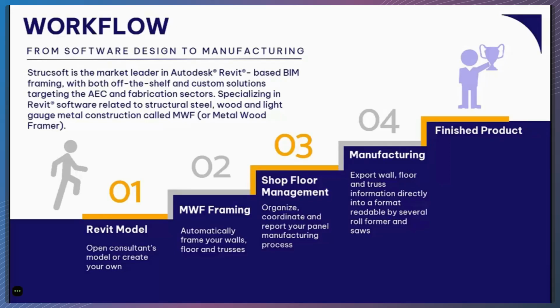So a little bit about the workflow now. Typically, our users will either get their Revit model from another consultant or they will create their own. And we will work directly in the Revit environment. We will recognize all of those Revit elements and we will frame them. So we will frame your walls, your floors, your ceilings, your flat roofs, as well as your slope roofs with trusses. We will recognize any openings within them and frame them according to user-defined criteria.